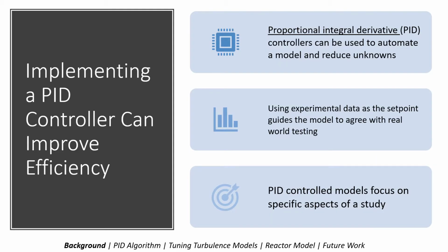My research is proposing that through coupling a proportional integral derivative controller, or PID controller, to a CFD model, one is able to circumvent the challenges that come with complex modeling in CFD while maintaining the ability to produce reliable data. PID controlled models reduce the unknowns when completing a run, as a model can be instructed to automatically reduce error without any user input.